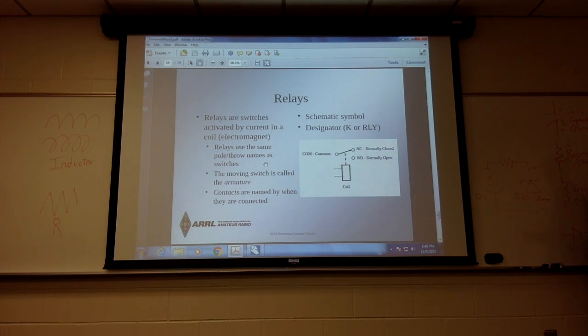The term comes from throwing a crowbar at an electric circuit and just shorting across the outputs, drawing an excessive amount of current and hopefully tripping our fuse or breaker. So if we can somehow trick this thing into shorting the output when it overvolts, then hopefully the fuse we put in line will blow, and that's over voltage protection.